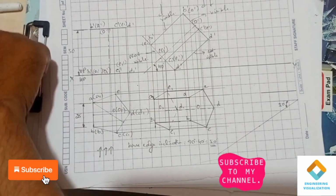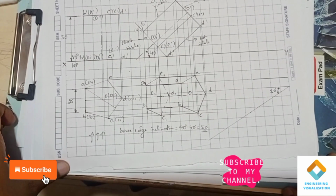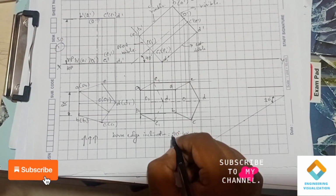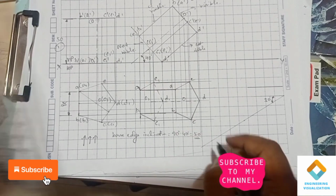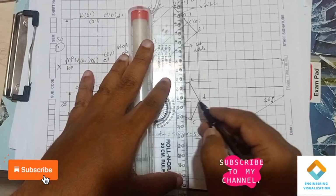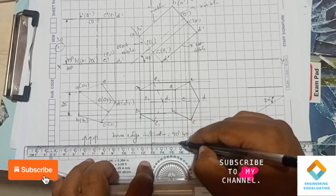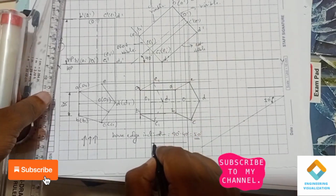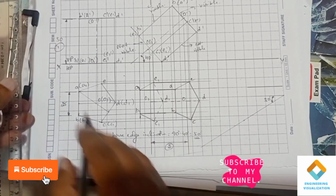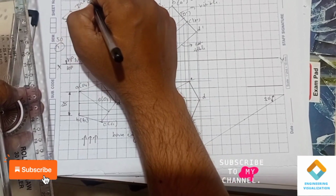Now we know that in the beta angle problem, it is with respect to the axis that we have to work. There are two axes given: the 50 mm front view, that is your first axis, and the second axis length is the second position top view. So this is your second position. We should consider this length as your second length for cutting the arc and finding out the beta angle. This is your second length. So the first axis length we have to use is this one, that is 50 mm, for cutting the arc.